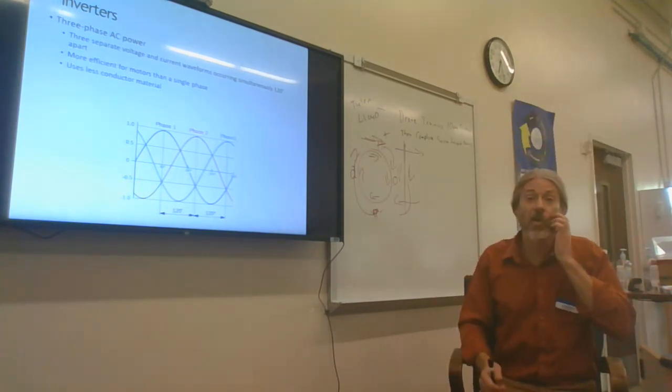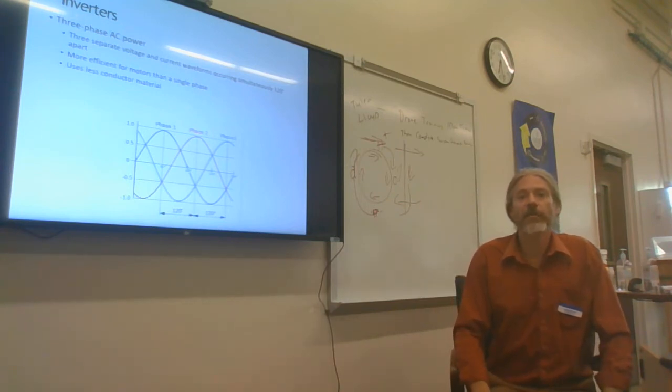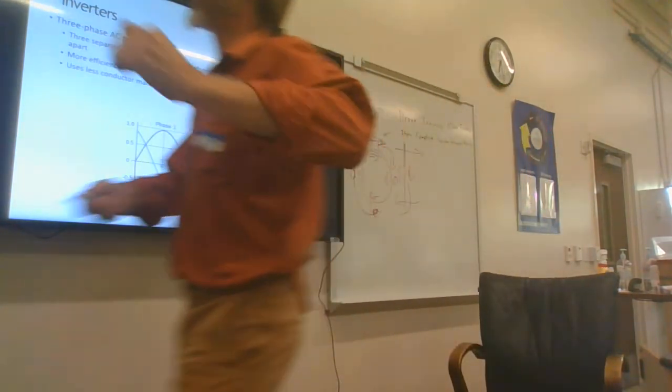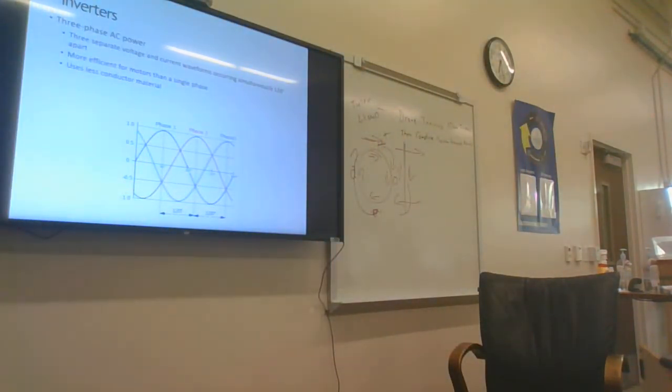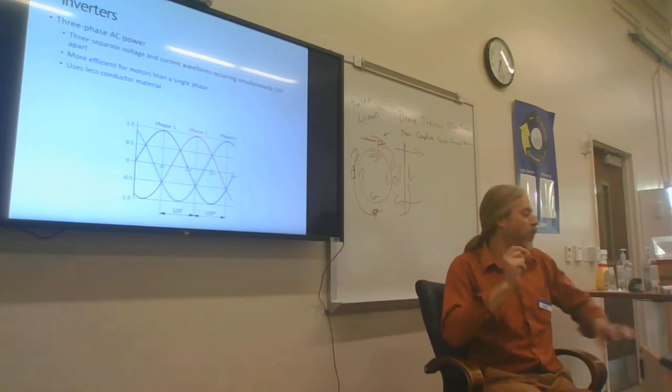So we also have what's referred to as a neutral in a 3-phase system. And the 3-phase neutral would kind of be like the return. It would go to the middle of this. So it could come out of this and return to here to the neutral. It could come out of this one and return to the neutral. And so if I have, let's say, 240 volt difference right now at this cycle between here and here, then I would only have 120 volt difference between either one of these and the neutral. All right. So there's more than one way to wire a 3-phase system. I believe that we do briefly touch on that.